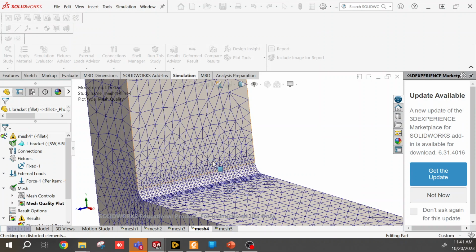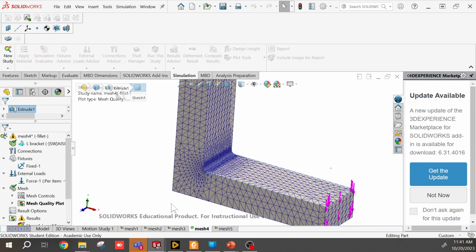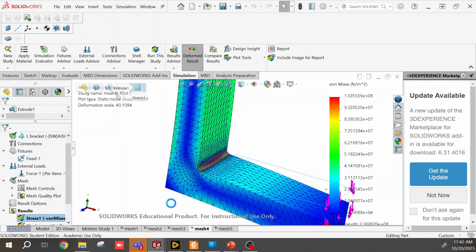So you can see, well, the mesh density in here changed a little bit, but the majority of the change was in the bulk area surrounding everywhere else. So if we rerun this, who has an idea of what's going to happen to the stress in this case? The fillet will change a little bit, but the rest of the area, I think it'll be dramatically different. I don't have the file to compare back and forth, so it's going to be hard.